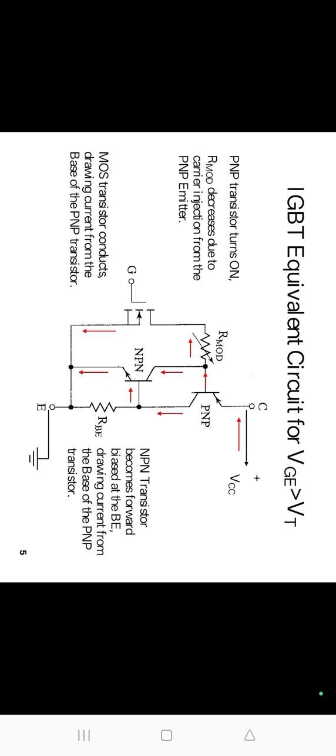This can be achieved by using special geometries for the structure of the IGBT. The circuit should be designed in such a way that the maximum specified current is not exceeded. Latch-up can also be avoided by increasing the turn-off time and controlling hFE of the PNP transistor.